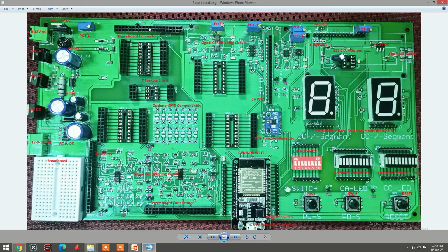Okay, because before we demonstrate the functionality of the board, which is replacing your power supply, DSO, function generator, and logic analyzer, first you have to make sure the board is intact, the board doesn't form any short circuits, and the board is properly powered up. Okay. And whenever you are mounting the components, any of your digital components here or piggyback boards over here on this connector, make sure the power is off.